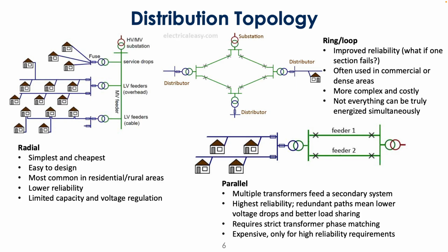It's one of the reasons why at the transmission level, we think about the grid in the US as partitioned into three main areas. There's WEC, ERCOT, and the Eastern Interconnect. And one of the reasons why they're left separated is because even though they all operate at 60 hertz, actually they're not in sync.